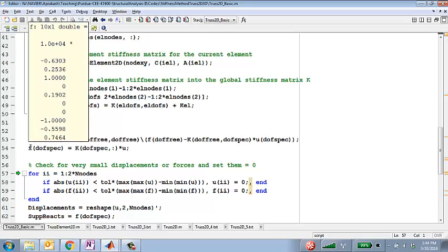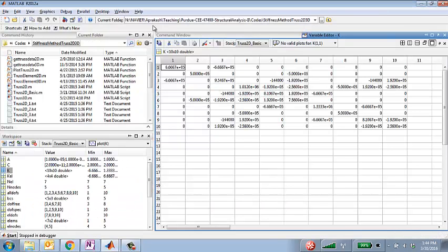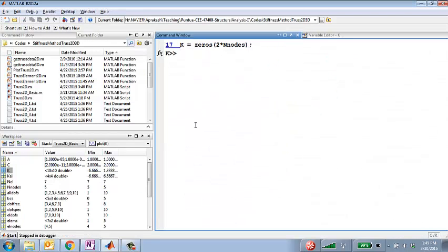I have the correct forces at all the nodes of the structure, including any external reactions. Let me ask you this. If I were to go to Matlab command window and say F, so this is the current value of F, which is the forces acting on my truss, including external loads, including reactions and everything. If I do sum F, what should be the output?